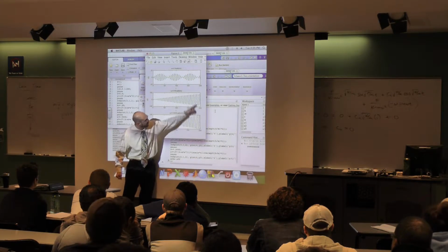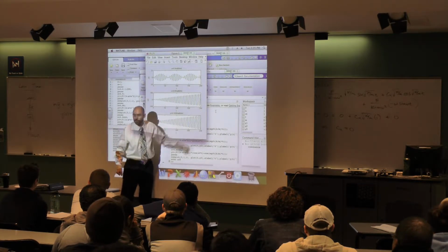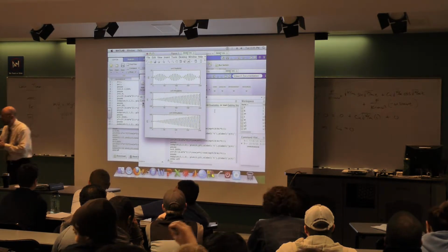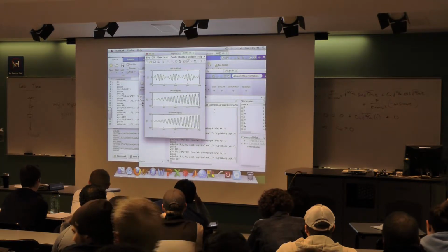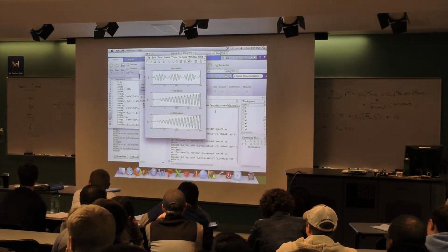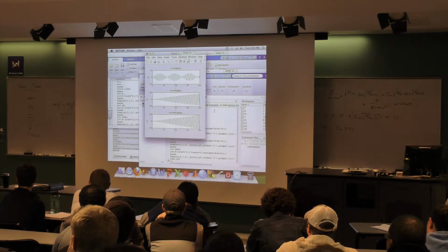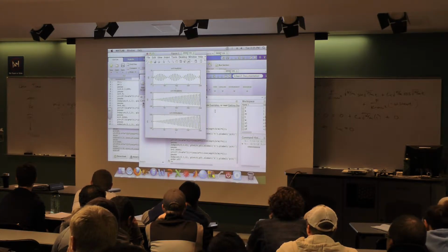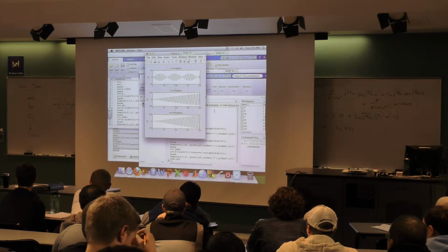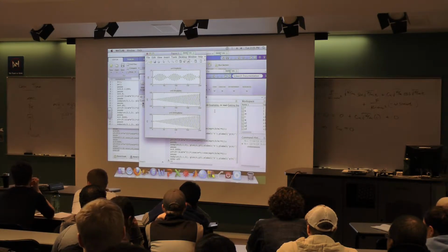A teeny bit increase in amplitude, right, out here. But essentially what happens is this is called resonance. If you are really, really close to the frequency, by the way, in your car, that's usually related to rotating unbalance of the tires, right? And so you've got a rotating unbalance there, and the speed is the frequency that you're spinning the tire, right?